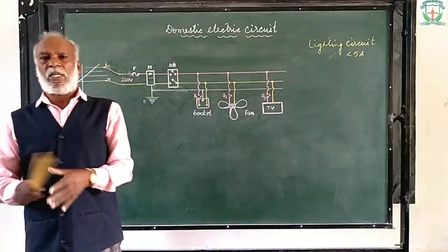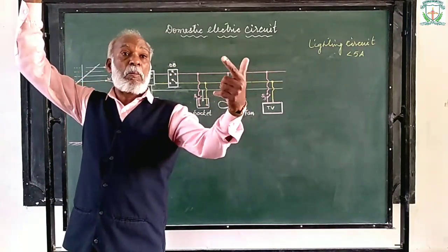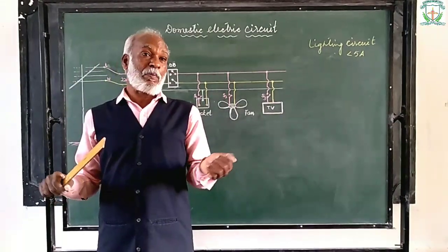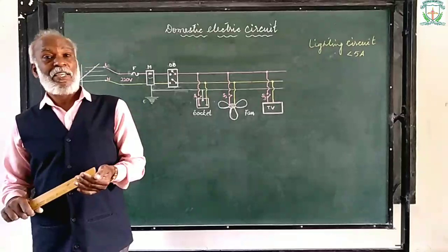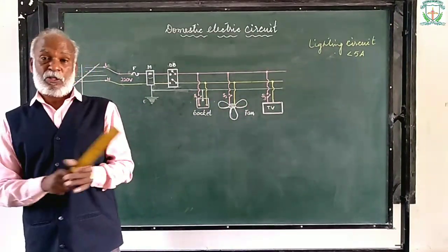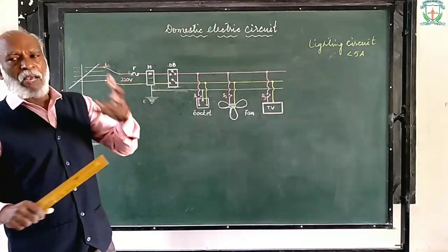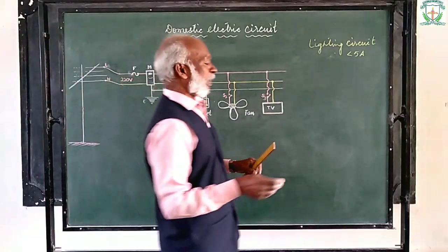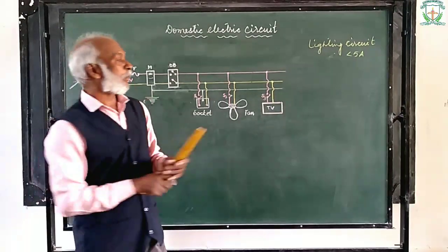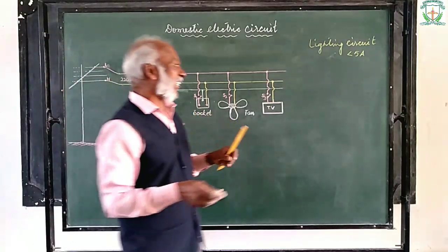Devices such as washing machine, microwave oven, your toaster grill, OTG, toaster cum grill, or your electric iron, electric press, the machines which draw heavy current, more current, say up to 16 amperes of current or even more, are connected to a separate circuit called the heating circuit.